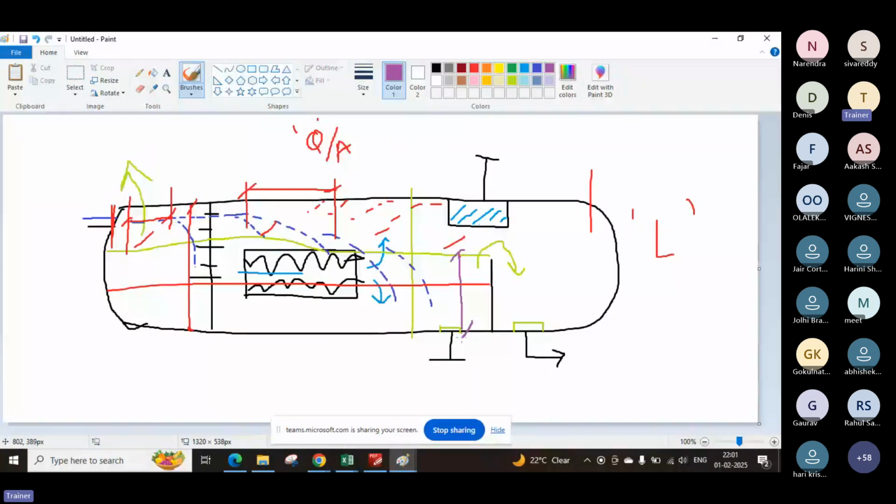Suppose we take an example of 1311. That is high liquid level. That is alarm to the trip 1 minute. Alarm to the low level alarm is again 1 minute, 3 minutes, and then suppose you have again 1 minute is the gap between the low liquid level and low liquid level, and this is the bottom one.